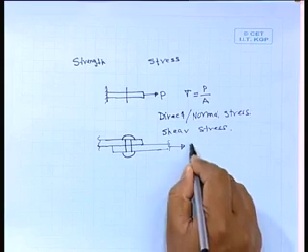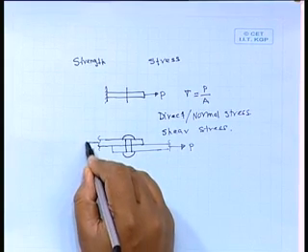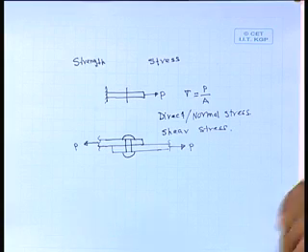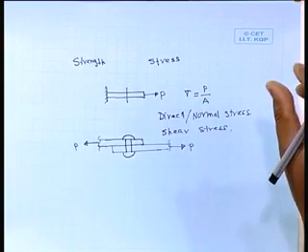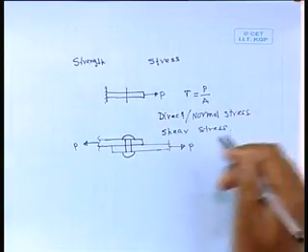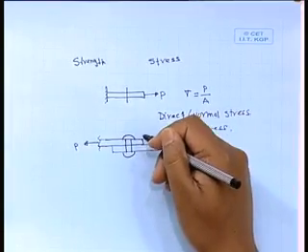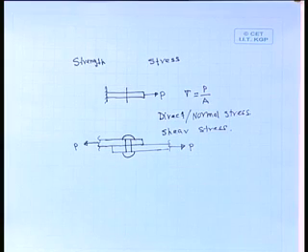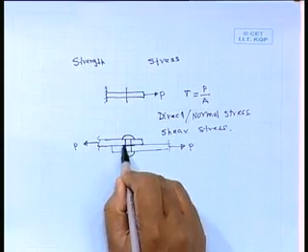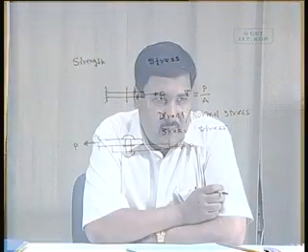Now, there is a load P this side and there is a load P the other side. Now, here you try to feel about the failure of the rivet. The plate which is below will try to move to the right side, the plate on the top will try to move to the left side. Now, along this plane the rivet will try to fail, right.